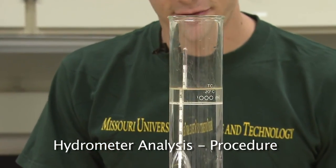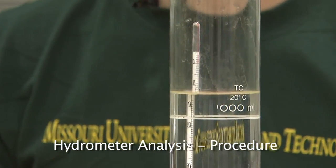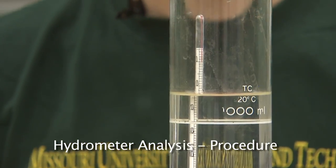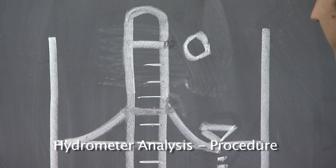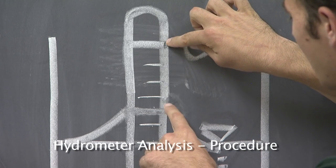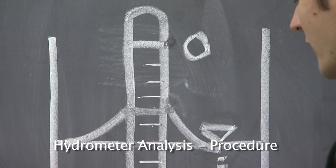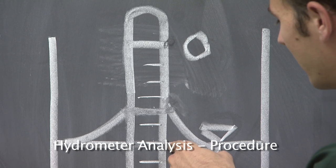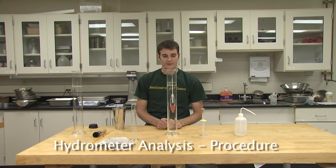The reading on the hydrometer staff from the top of the meniscus to the 0 mark is the zero correction factor. Also noted is the meniscus correction factor. The zero correction factor is the distance from the 0 mark to the top of the meniscus on the hydrometer staff. The meniscus correction factor is the distance from the water level to the top of the meniscus on the hydrometer staff. Record the meniscus correction factor and the zero correction factor on your data sheet.